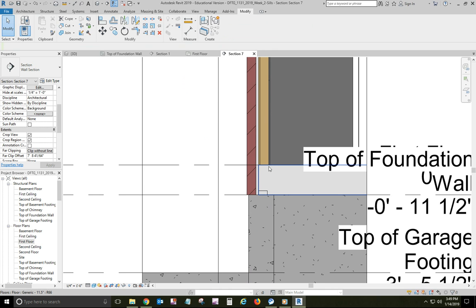I've already fixed it here, but what happened is that for some reason the stud wall was coming all the way down, the floor did not cut it out. So do the join command, just go join and choose the floor system and the wall system, and it should cut the wall system out so that our invisible floor sticks all the way through there.